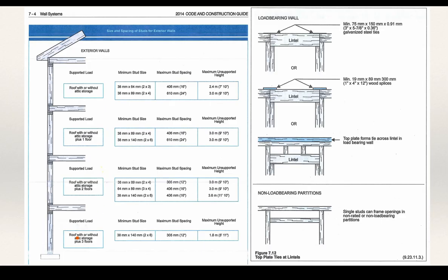So in theory, you could have a lintel down here at the bottom. So if we had a pressure-treated wood foundation, you could have a lintel in a pressure-treated wood foundation. This is when we have a foundation that's not concrete. It's actually made out of 2x6 or 2x8 pressure-treated wood. So let's say you had a walkout basement, you could have 1, 2, 3 floors plus the roof load at the top. So that lintel would be carrying a lot of weight. And so the span on that lintel would be drastically different than the span up here on this upper floor just carrying the roof.